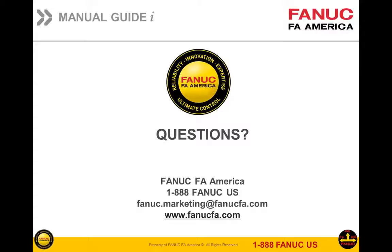Another question. Can you program a Davis head for a horizontal boring mill with manual guide eye? You might have to, I'm not sure if there's parameters to make that work. We could possibly set something up in a fixed form to make it work, Mark. And that's what's good about fixed forms. Things that we can't allow for parameter-wise, sometimes we can put something in a fixed form to make that work.